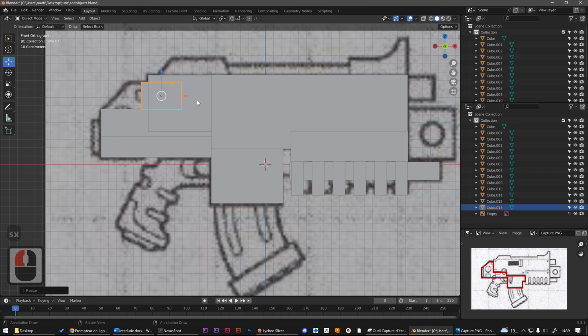So for the barrels, I'm going to explain something to you. Since now, when we created objects, let's create a cylinder to show you. We could have thought that Blender always places new objects at the center of the world, since an object is created at the crossroads of the three world axes. And well, actually that's not true. In fact, an object is always created where this small target, which you see here, is located. This target is called the 3D cursor.